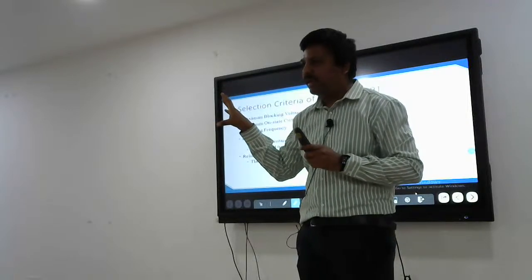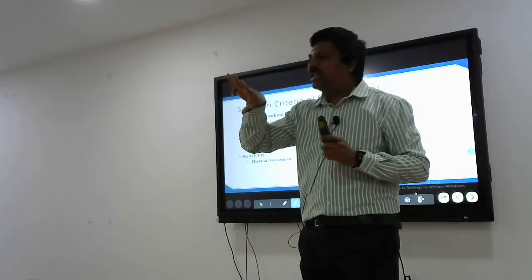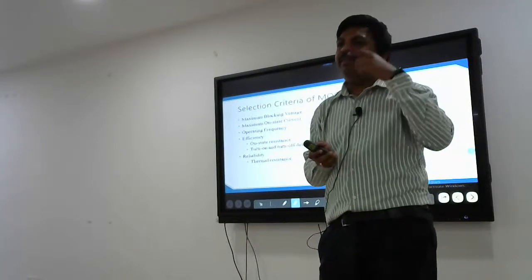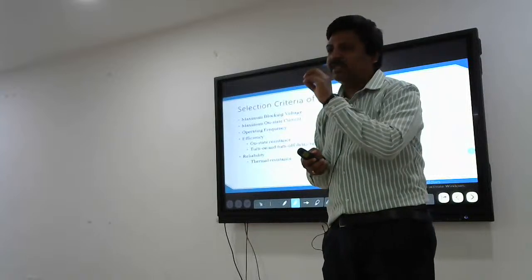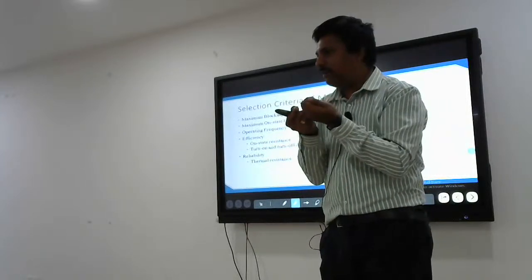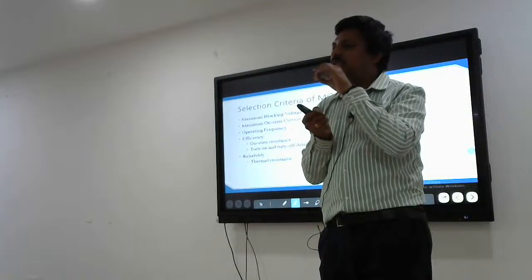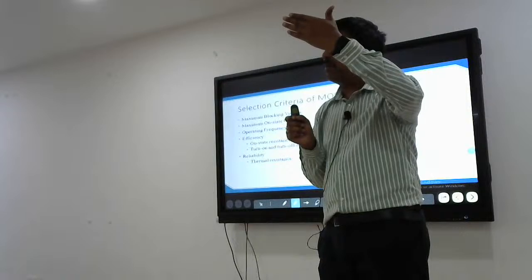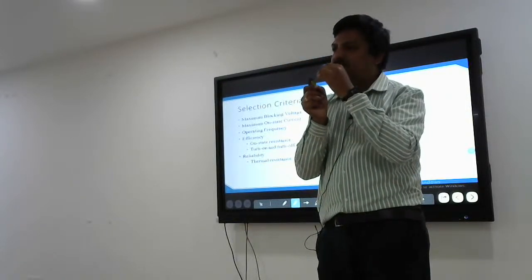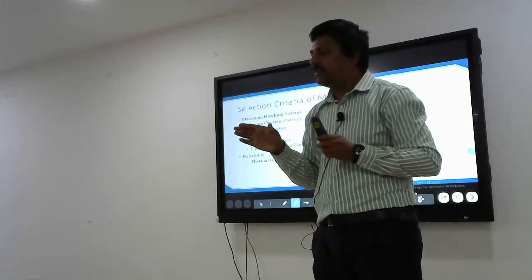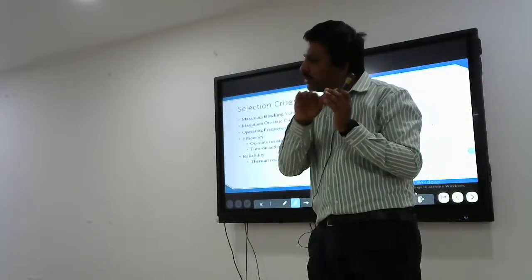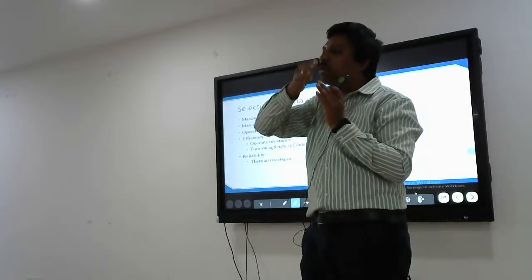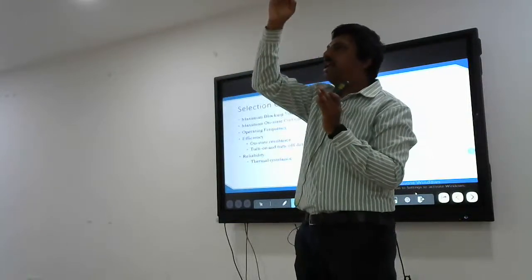For example, a MOSFET has three terminals, right? What are the three terminals? Gate, source and drain. Gate is a metal part, and source is also a metal part because we are giving a contact. Between gate and source there is a dielectric, so there is an inherent capacitance. The dielectric between the two parallel plates forms a capacitor, right? If you give a pulse, the capacitor will not allow the voltage to change from 0 to a higher value immediately. It makes the voltage profile move slowly to the higher value. It will not move directly.